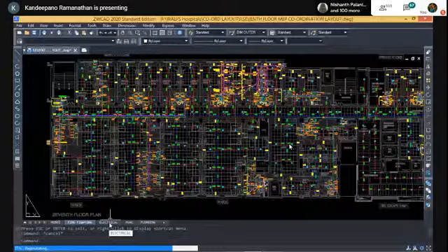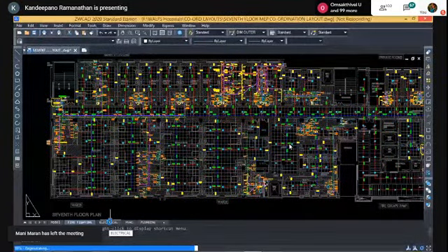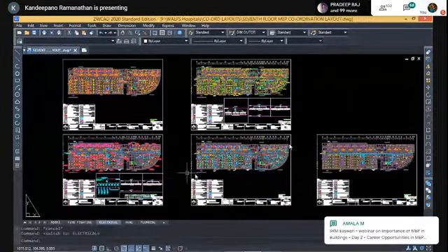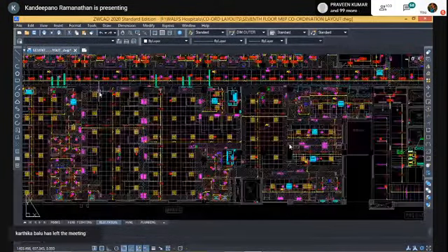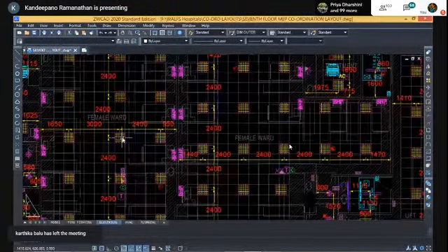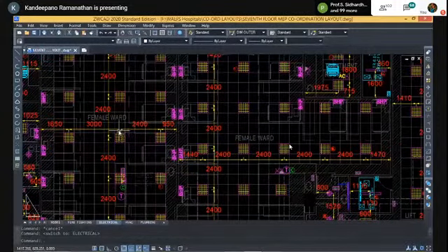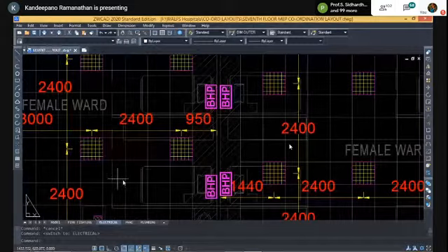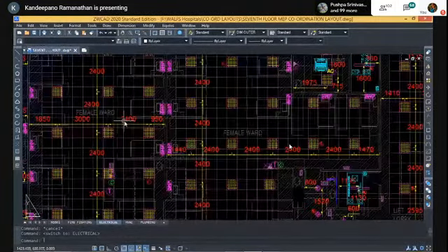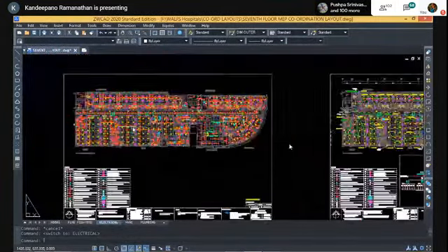Electrical drawings. After designing the electrical systems, the designers make electrical drawings and put them in place. Normally we have 5 electrical drawings for every floor. This displays only the fittings and the dimensions: a 600 by 600 tube light fitting in the false ceiling, and the distance between them is 2.4 meters. You can see this clearly now. This kind of drawing is the layout of light fixtures.